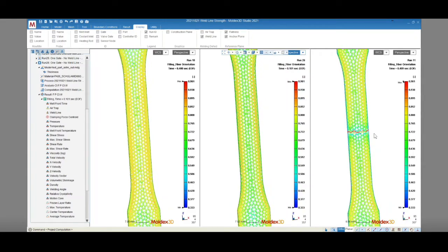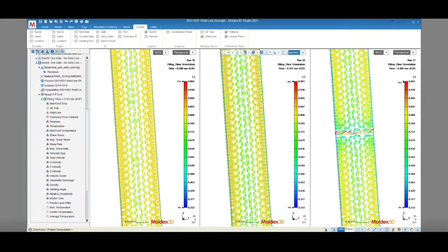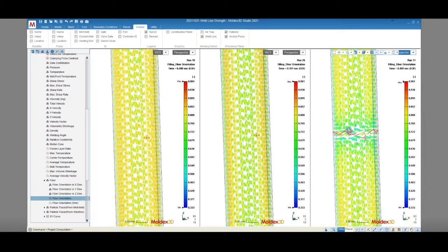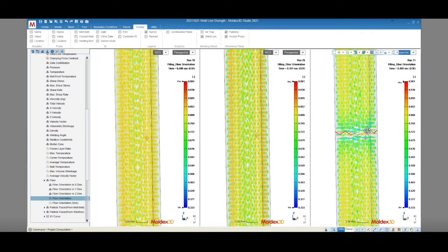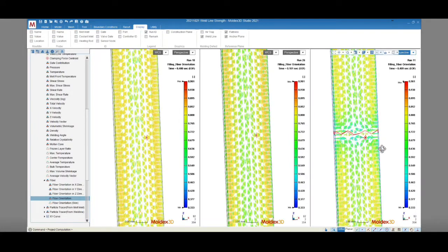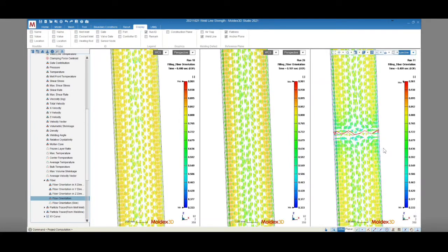Glass fibers are added to plastic materials because they stiffen parts and help them stand up to external loads without excessive deflection. To get that benefit, the fibers must be oriented in the correct direction. When designing a part, how do you know that you'll get increased part strength and stiffness where you need it?